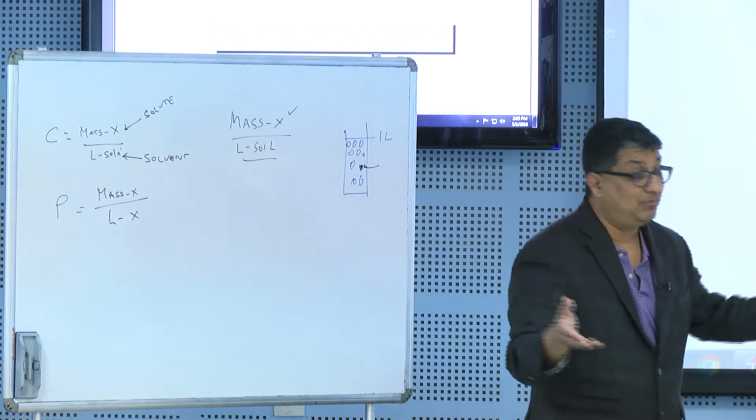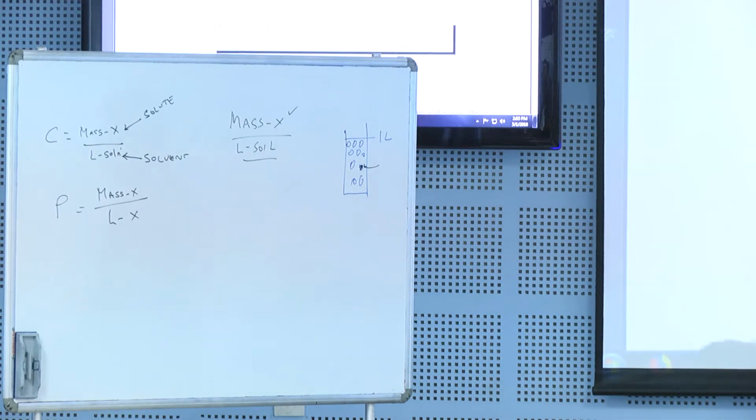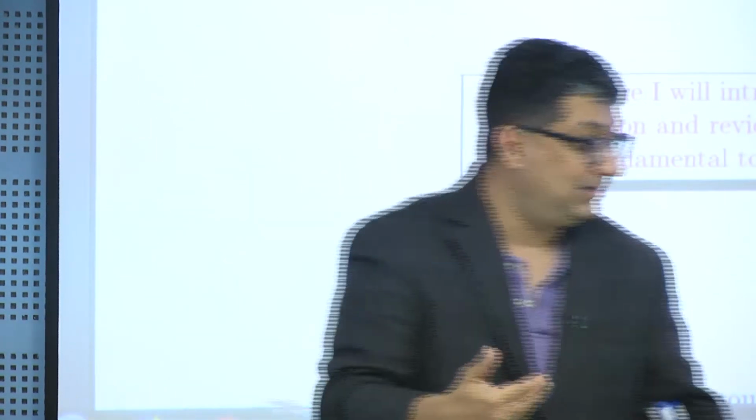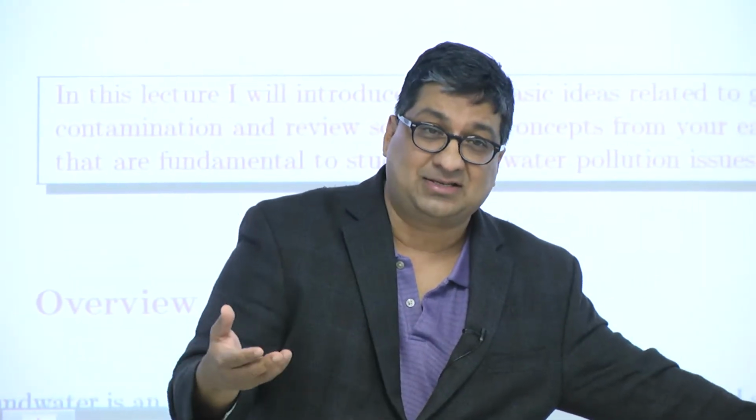So in the morning, Dr. Cecilia talked about subsidence, right? So what happens during subsidence? Compression. So we have water, we pump groundwater out, and it causes subsidence. The reason that's causing subsidence is because some of that force, or the stress, that's being provided on the aquifer by the atmosphere as well as all the overburden on the ground, part of that is being taken up by the sand grains, part of it is being taken up by water. So if I remove that water, that excess stress now has to be taken up all by the sand grains or the aquifer material.